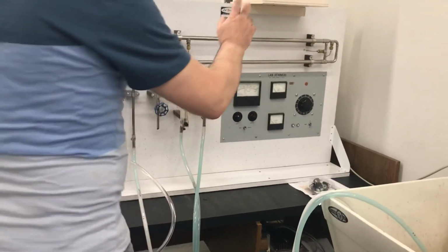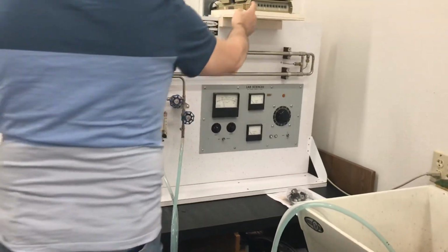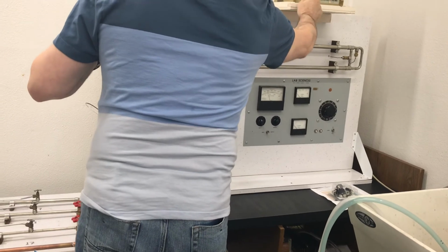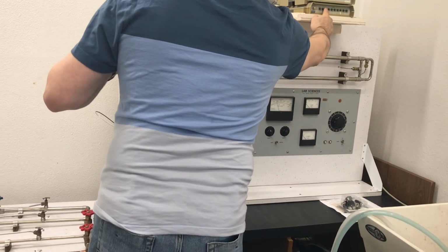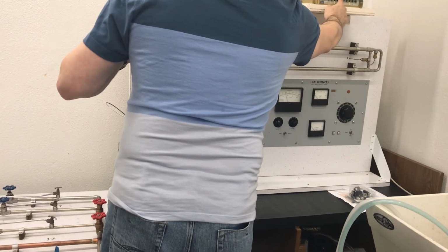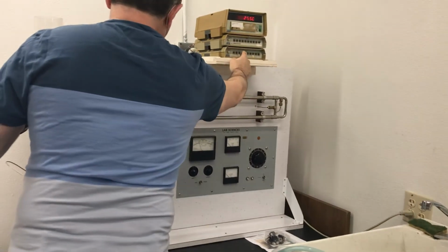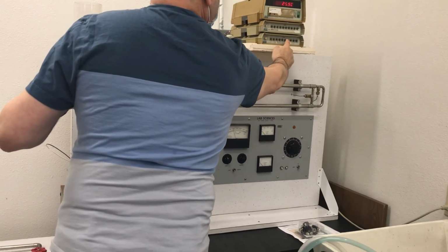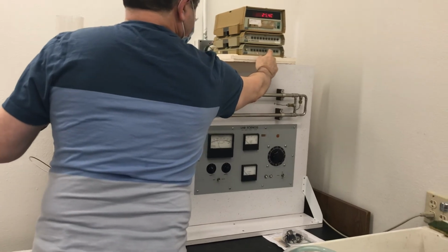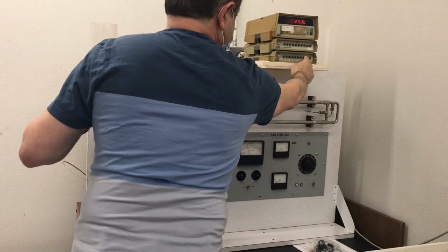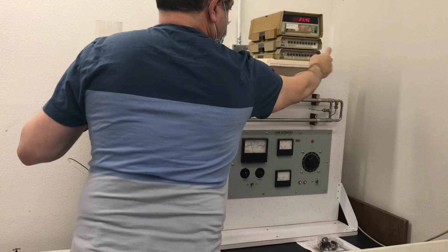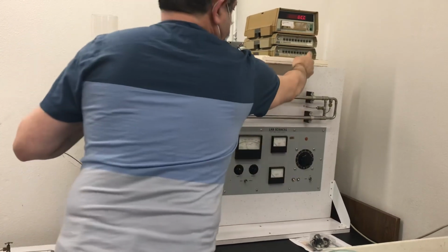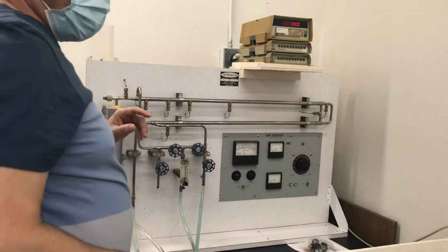Okay? So then what we do, once we have reached steady state, the only thing we do is go, okay, 1. Now something happened in here. Okay, so thermocouple 1, somehow it's not working very well. 3, 4, 5, 6, 7. Okay, that's TC out. This one should be out of channel, and they should be out of channel because we don't have thermocouples associated with them.